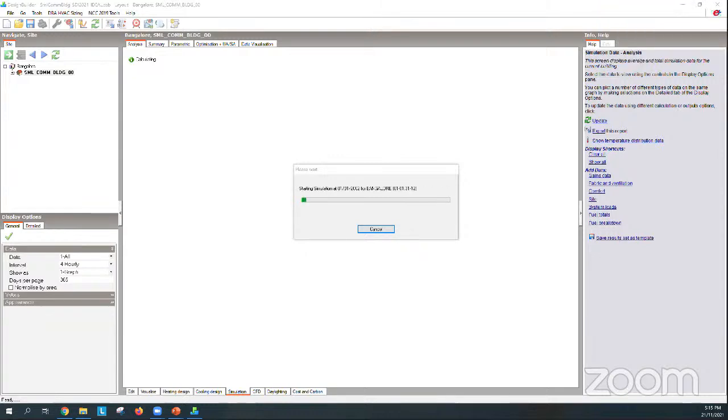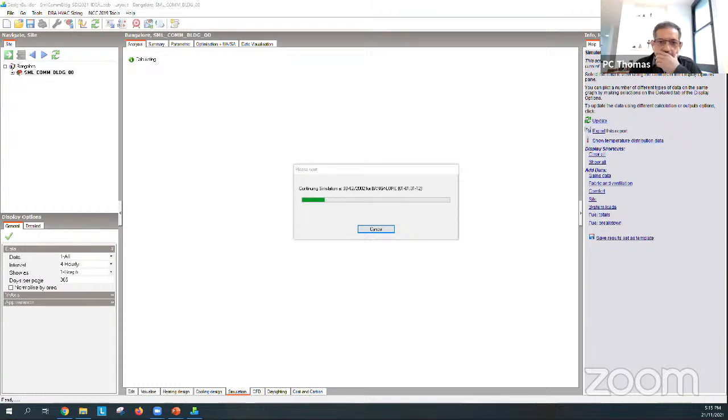Aha, okay, that's a good question. There's a couple of questions here. One is, while designing the shading for an opening, how do we decide the critical day for which it has to be designed? Now that's a very good question. There is actually no critical day, because as the sun moves in the sky, it has a different impact on the amount of cooling that's required. So you do want to look at the annual outcome.